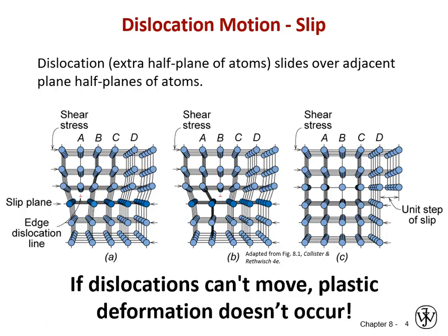So the next layer of atoms down below the end point of the dislocation, that's colored in slightly darker blue, that is the slip plane. And the higher the atomic packing fraction of that plane, the planar packing that we learned in chapter 3, or we learned in our crystallography section, irrespective of the chapter number, the easier that edge dislocation will move on it.